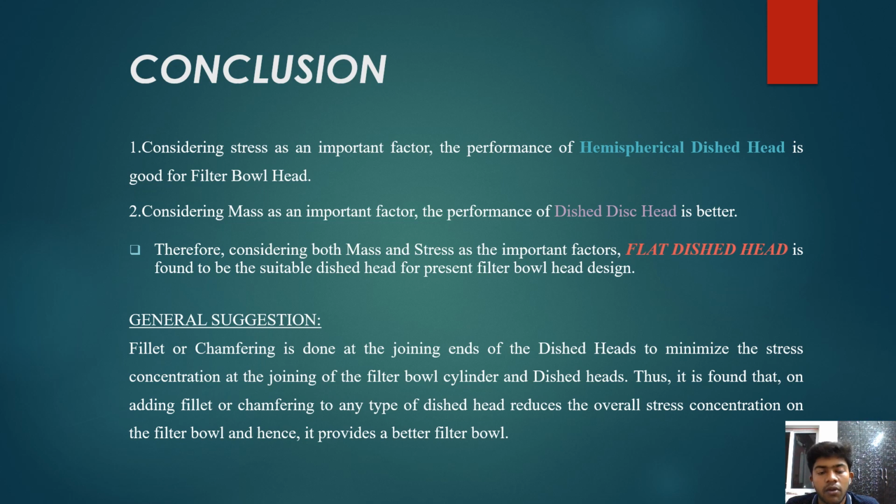But the problem is to find the most optimal solution, that is considering both stress and mass as important factors. We found that the flat disc head is the most suitable dish head for the present filter bowl head design. Hence, the flat disc head is the most optimal filter bowl head for the given filters.